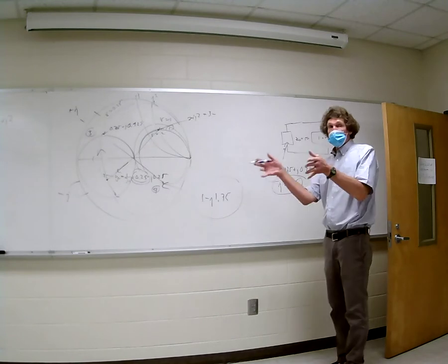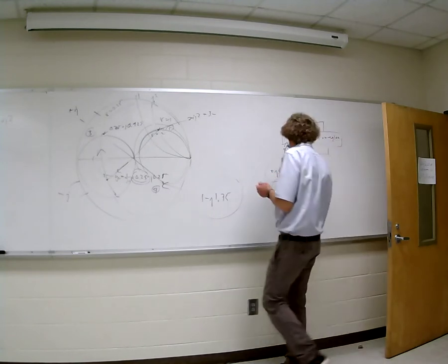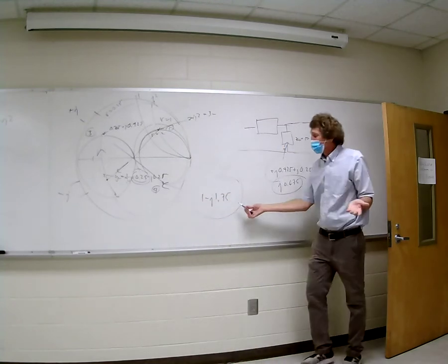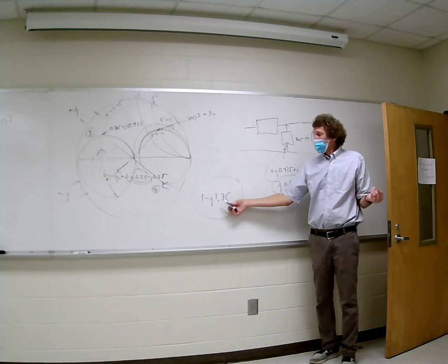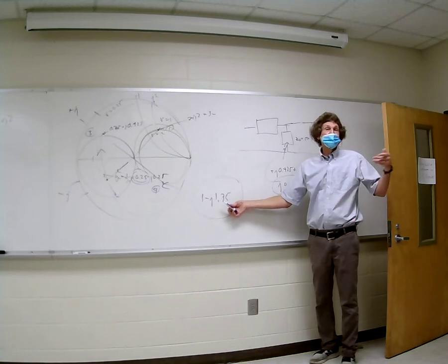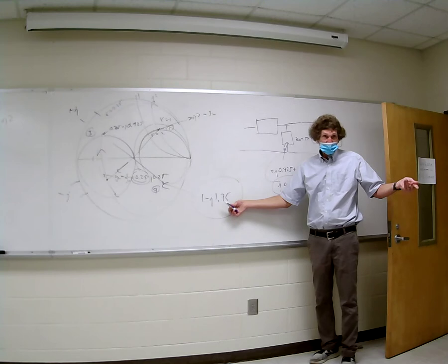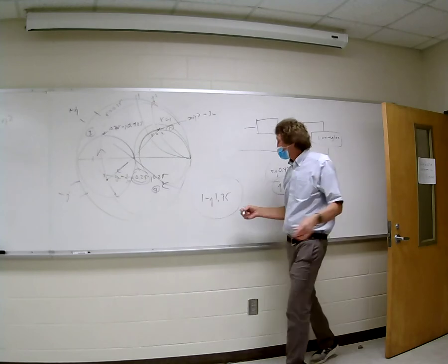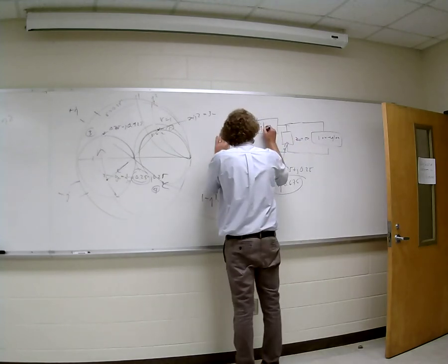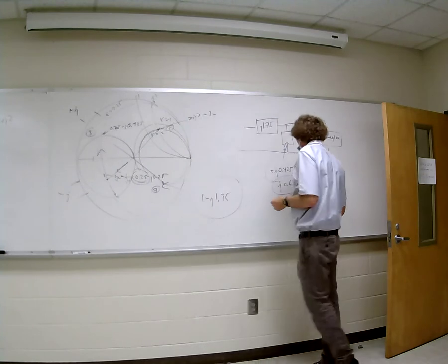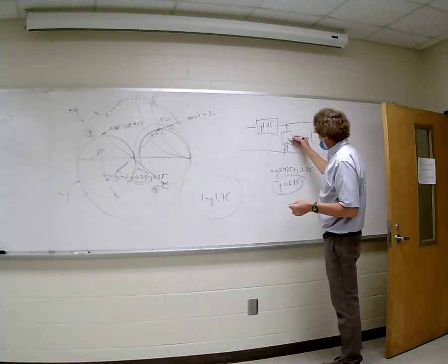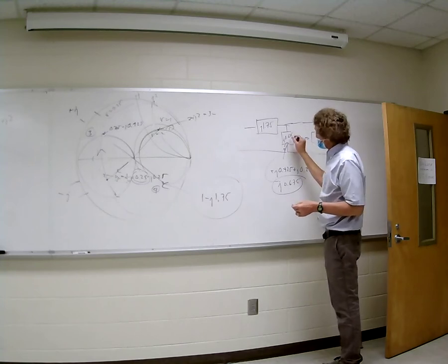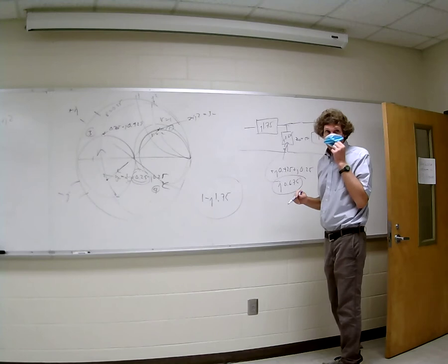So we're going to add a normalized impedance. What's the value of the normalized impedance? Just look here. What does it have to be if we want to get rid of minus j 1.75? We add plus j 1.75. Correct, class? So I just add j 1.75 right there. This one's j 0.675. Right? And that's admittance, that's impedance. They're both normalized, correct? Yes?